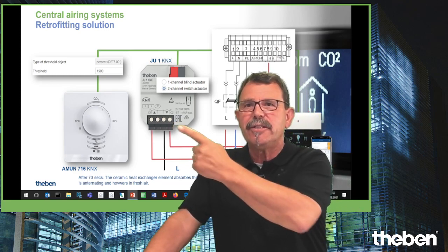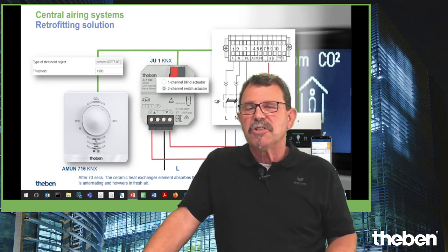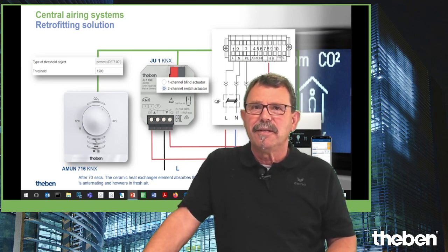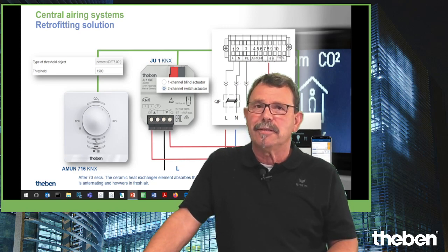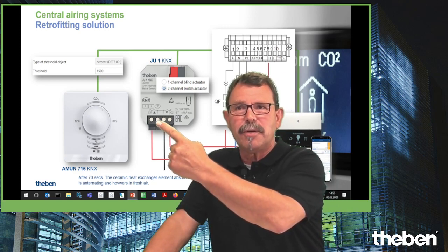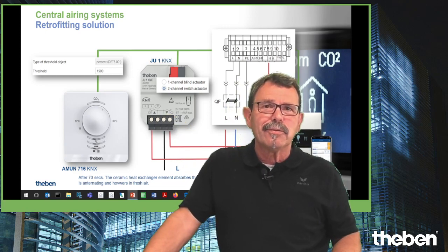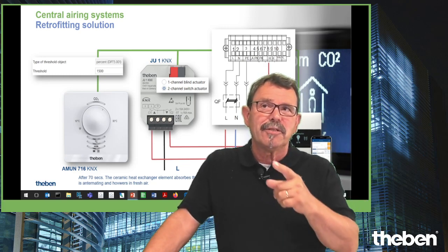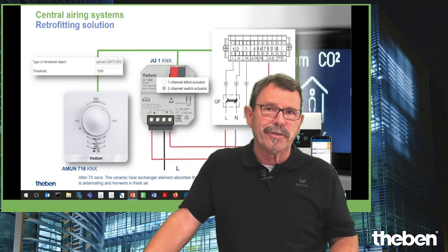And then I take here an actuator, a flush-mounted actuator. Doesn't matter if, let's say, twisted pair or RF, doesn't matter. But in this example I took a shutters and blinds actuator. Why this? Because with our shutters and blinds actuator, we can control these two relays totally separately. For shutters and blinds, you need the up and the down control, but you can set this shutters and blinds actuator as a 2-channel flush-mounted actuator.